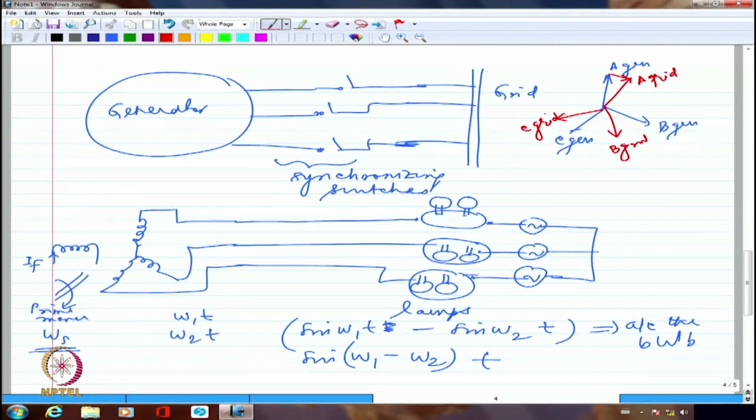If the phase sequence had been different, very clearly I am going to have this rotating in this direction, whereas this is rotating in the opposite direction. That's what it means by phase sequences are different. As simple as that. Are you getting my point? Instead of having ABC, if I am having ACB, that means it is rotating in the opposite direction.